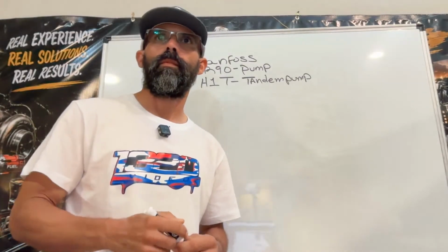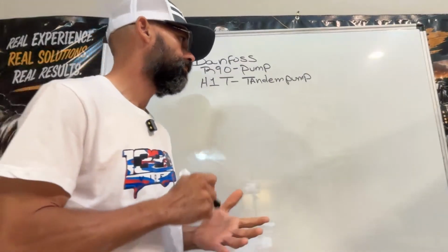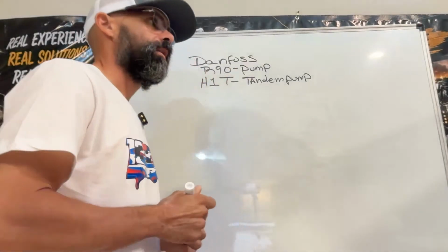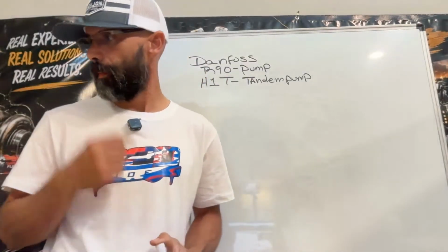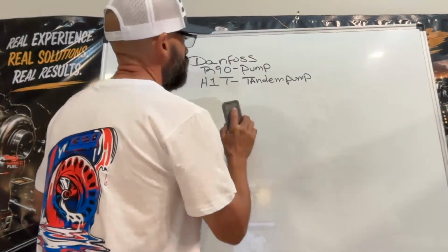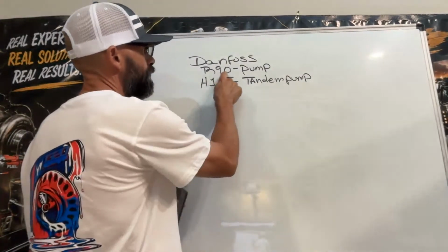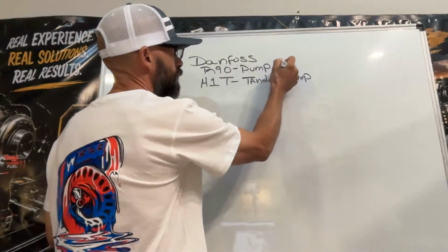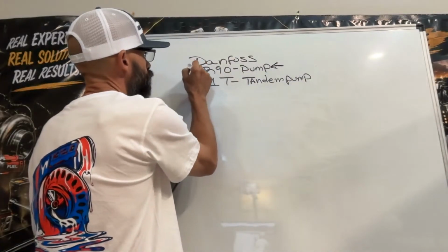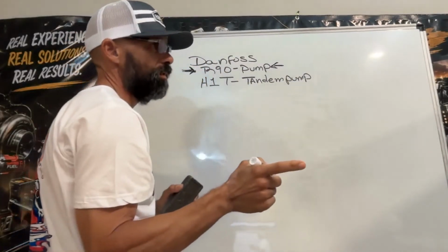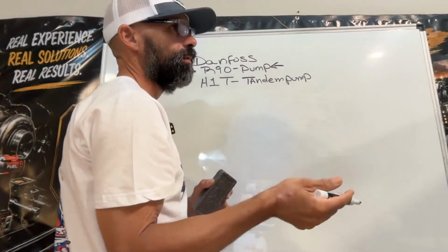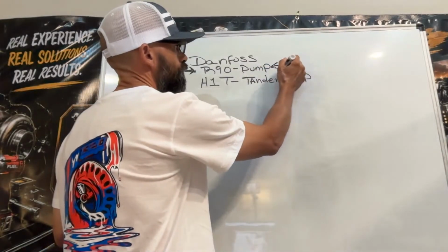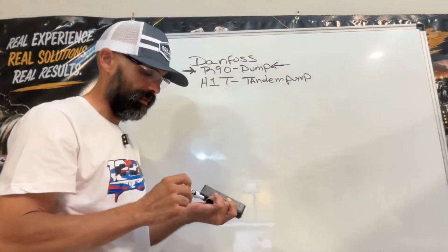The equipment, right? So going back to the hydrostatic closed loop system, they always need charge pressure. So where's the eraser? Okay, right here. So let's talk about the R90s, these pumps right here. This one is found on 2440s, 3650s, so medium size to the heavier drills. They have their own charge pump system.